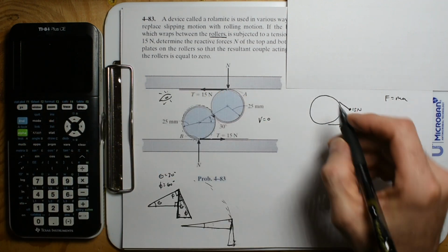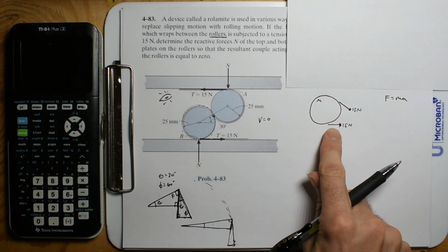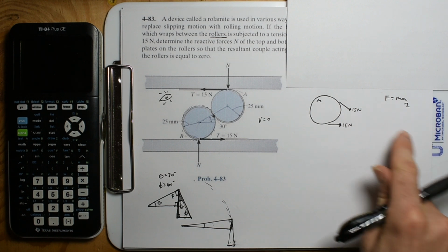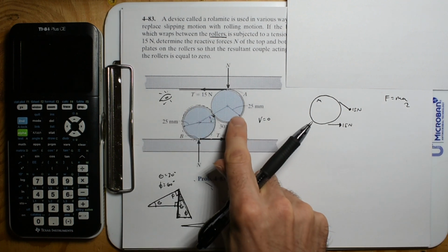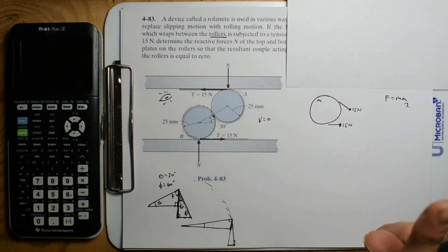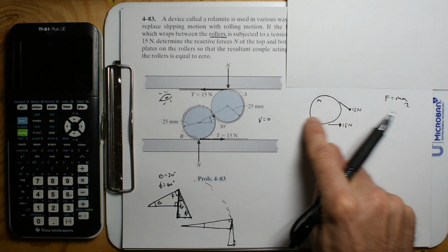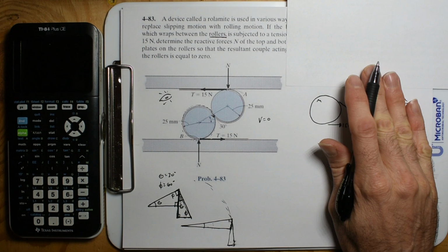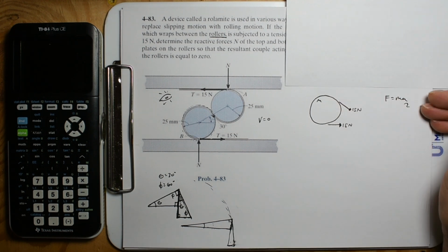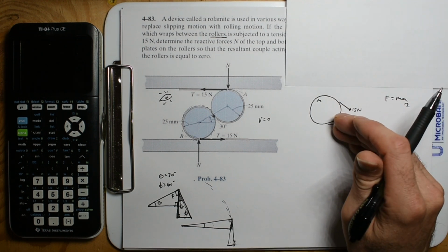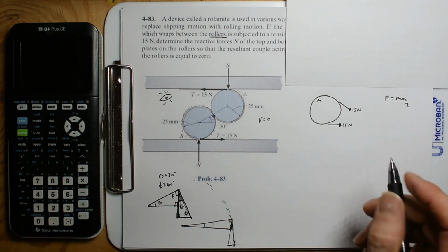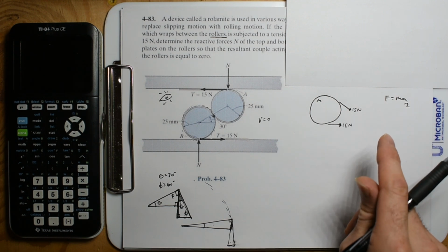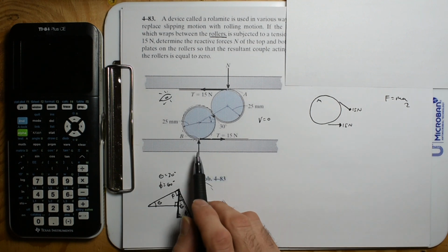Okay, so we have this mass of the roller, and then we have a force on it. So we are going to see a change in velocity in those directions. But we go back to Earth, and we know we don't see a change in velocity. So we need to have forces that balance these. Besides the equations for statics and setting up the free body diagram, the other most important thing is to identify where there could be other forces. And the places that you're going to have other forces are at your contact points.